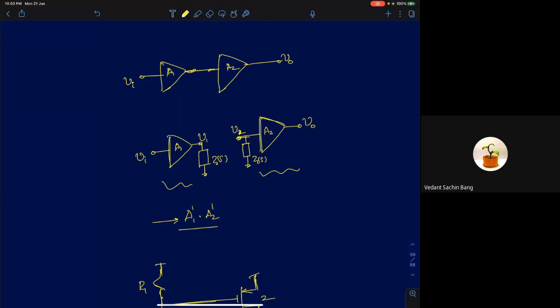Now that we have understood circuits to a good level, we should be able to see that in such a circuit, you can pick any node and let Z2 of S be the input impedance looking into this node. Then you break the loop and load the first stage with the input impedance of the point where you broke the loop.